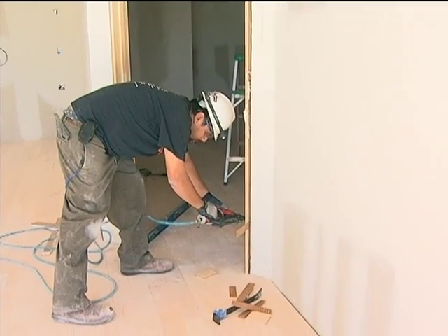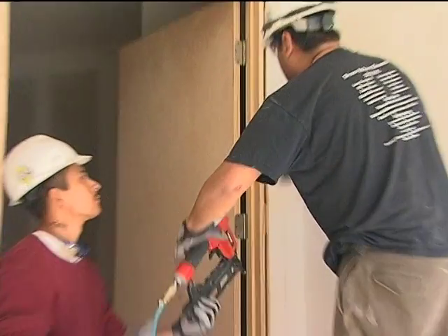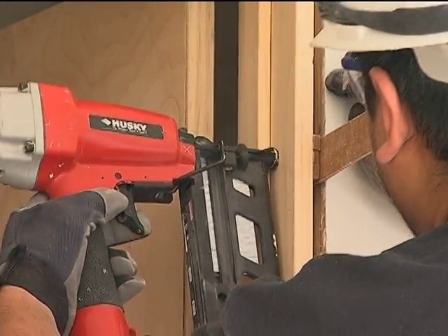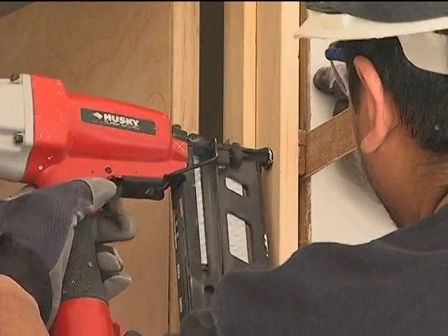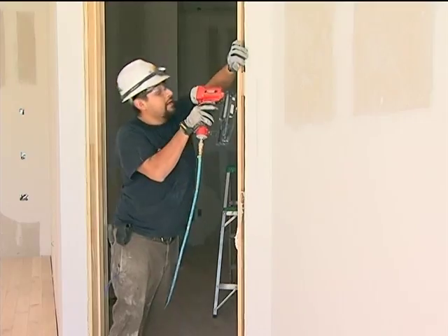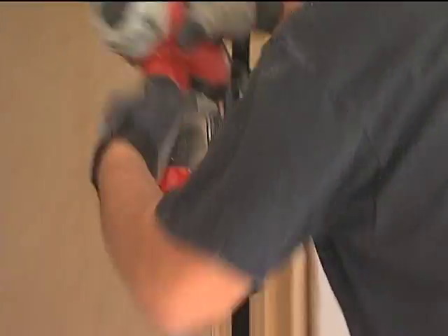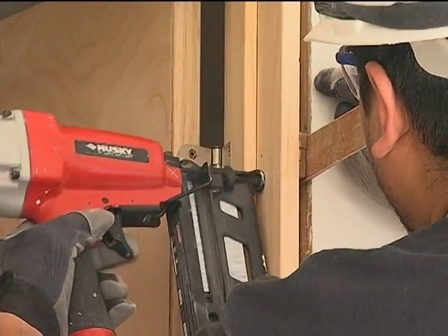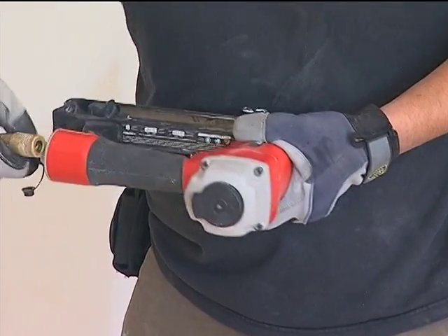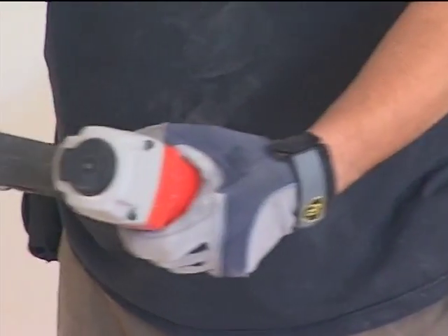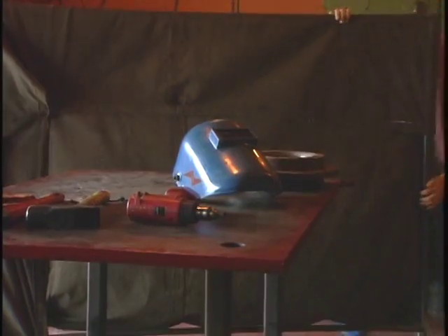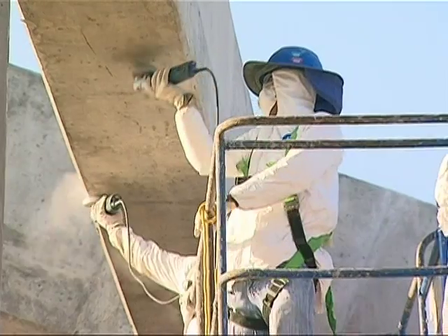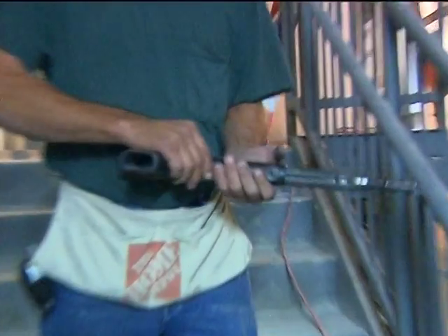Pneumatic tools that shoot nails, rivets, staples, or similar fasteners and operate at pressures more than 100 pounds per square inch must be equipped with a safety device that prevents discharge unless the muzzle is pressed against the work surface. Never point compressed air guns or any tool at anyone. Use screens where practical to prevent nearby workers from being hit by flying fragments.